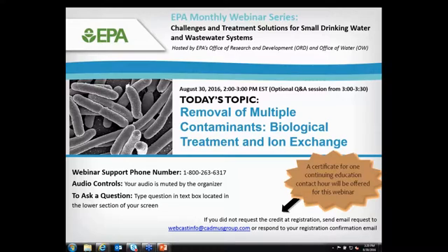With the potassium chloride, you're now using potassium as the counterion instead of sodium. We think that has some benefits both for the treated water and for disposal. The challenge is that potassium chloride is a bit more expensive than sodium chloride. So, do those benefits in terms of the treated water and disposal outweigh the higher cost of potassium chloride over sodium chloride?